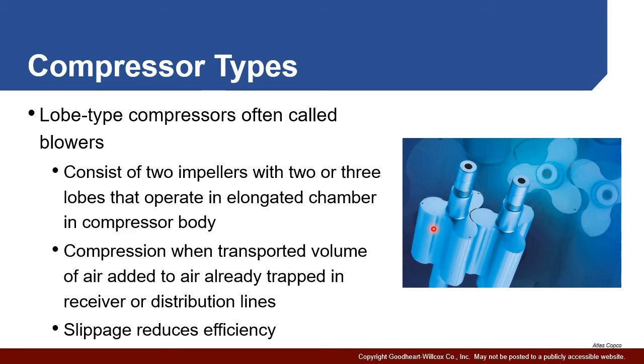As a result, they're really not capable of generating very high pressure. They are single stage, right? You don't have multiple stages here. So they're generally actually referred to as blowers, because they're only going to generate somewhere around 20 psi at the maximum. As that pressure goes up, there is a certain amount of slippage or leakage that's going to take place, and so they're not particularly efficient for that.